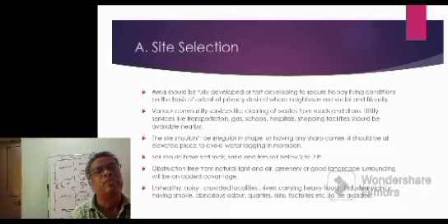Then soil should be soft rocky type, or maybe a sandy or firm soil, 2 to 3 feet below the ground level, because you should have a firm soil on which you will place your foundation. Otherwise, it should have the required bearing capacity. So that we have to take care of.